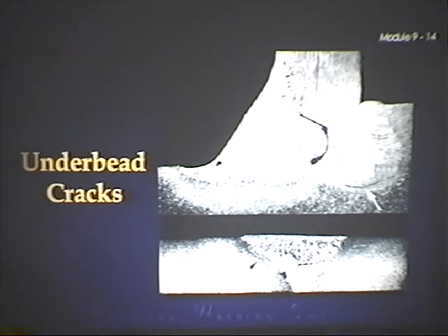That's a mouthful. But basically, what molecular hydrogen is, when you're welding, there's all kinds of forms of hydrogen around. There's hydrogen in the air, there's hydrogen in your breath, there's hydrogen in any moisture. If you have grease or oil or anything on your gloves, there's hydrogen in the petroleum products from that. Hydrogen can get dissolved into the weld metal. So what happens is this hydrogen forms molecules, and it nestles between the grain boundaries of the base metal.